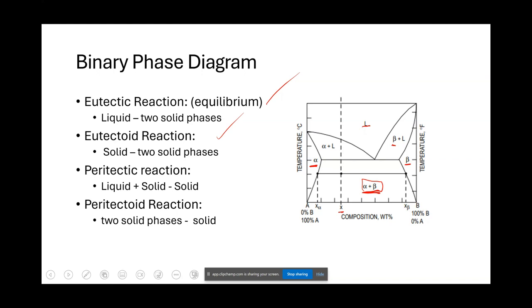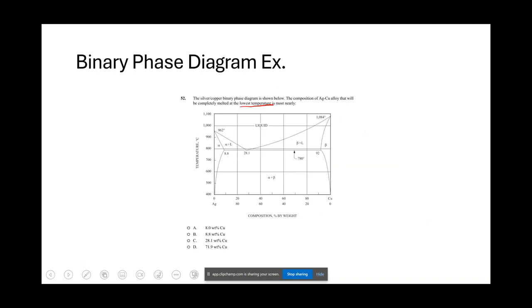So in this case, it would be something as of right here where there's that balance between the liquids. We don't have that directly, but we can tell through this graph, this is the lowest point of the solids and liquids combined. You can see the line coming through all the way over here. That's representing the solid and liquid break. And this point right here, as mentioned, is the lowest temperature at which the alloy will become a liquid. So in this case, C would be our answer.